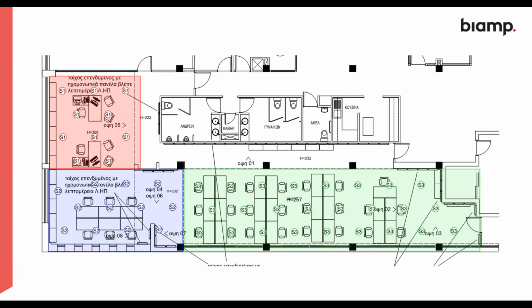When would we use active over passive emitters? From Jonathan. We would use active emitters if we wanted music or paging. I would also use active emitters if we have a very low ceiling, because the lower frequencies will upwardly mask the higher frequencies. So that can give you a slightly more effective sound masking system. And also, if you had a high ceiling where you needed a bit more power to come down, or you wanted a higher level of sound masking.